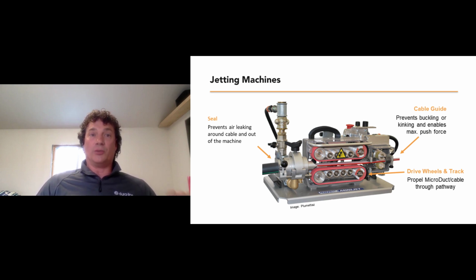Versus in a traditional, you would connect on to the front of a traditional fiber with a bull line pull tape, and you would pull that product from one end, requiring that cable to have a very high tensile strength. So if you can imagine, you've got air that's swirling around the cable and picking up that cable and carrying the entire cable along that microduct, and that's essentially the technology and how it gets installed. So it gets installed at very high speeds. You're talking 300 to 500 feet a minute. And very easily on job sites, we've installed a kilometer of cable in approximately 18 minutes.